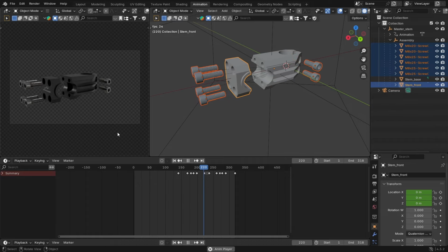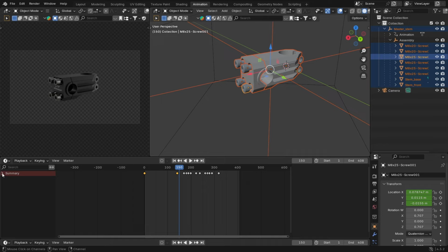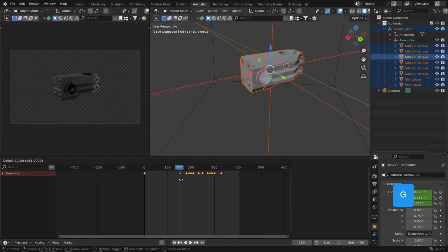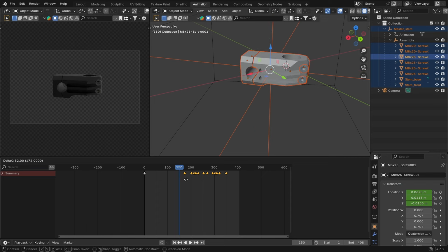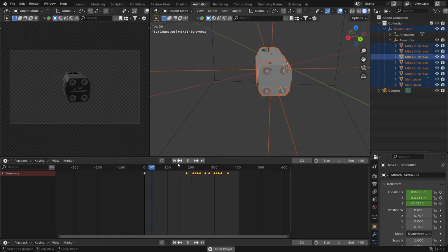One of the advantages of using keyframes is that they're non-destructive, meaning you can always revert to earlier keyframes and make adjustments. In this case, with all the meshes selected, we can see the master keyframes that control the initial rotation. By shifting all the keyframes after the rotation to the right on the timeline, we can effectively lengthen the duration of the rotation, thus making it slower.